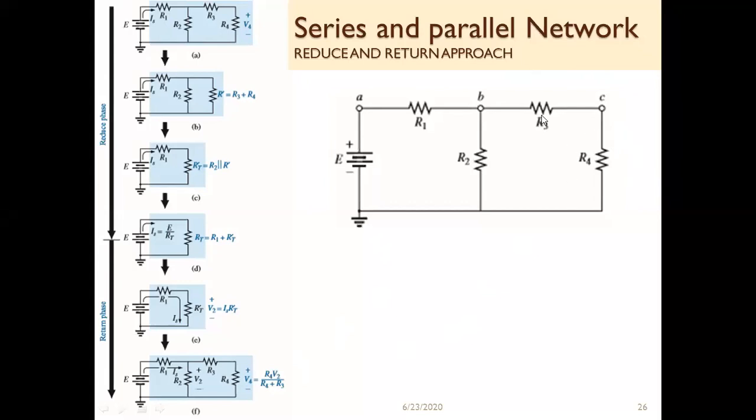If you want to find out the voltage over here, the same formula you can apply, but instead of R4, you will put R3 over here. But if you determine the value of R4, then R3 is very easy. You do not need to apply the voltage divider rule again. It would be lengthy.